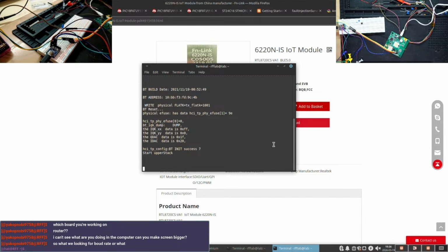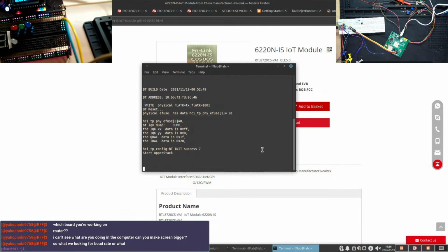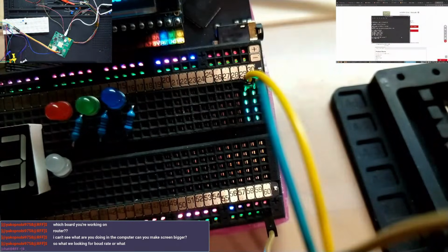Oh, that's kind of fun too, as you can see with the jumper list. When I'm actually sending some UART over it, it makes some noise across the line. You can see it flash. So that's cool. You can see that that's actually going across the wire to the device, and it's not doing anything. So, I wonder if there could be some hidden commands in here, or maybe it's just not even listening. It could be something.